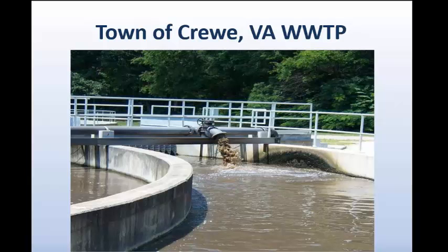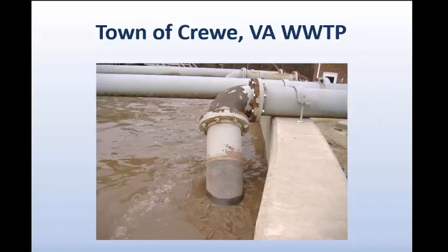So we discontinued the aeration and we added, and this is our plant, you can see we welded on extensions onto that discharge piping so that we had our discharge point below the surface of the water, or the mixed liquor, in our anoxic zone channel. This elimination of the surface agitation and the additional oxygen from the aeration at the beginning of treatment to the ditch provided us with the target environment with regards to dissolved oxygen and gave us exactly the results that we were looking for.